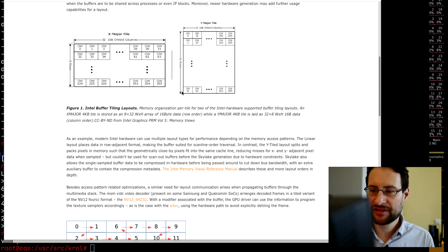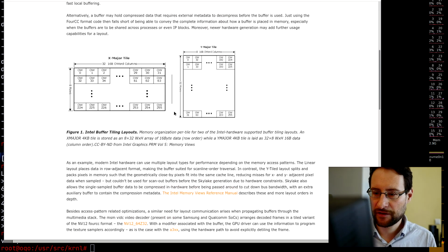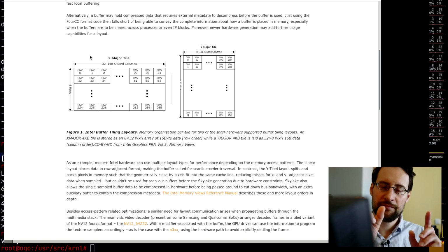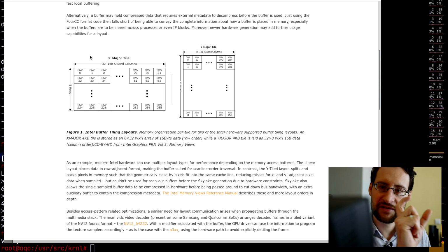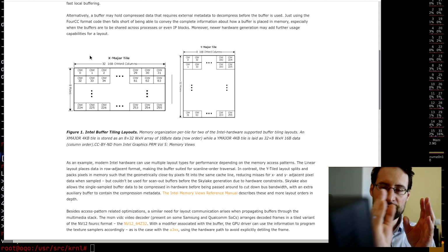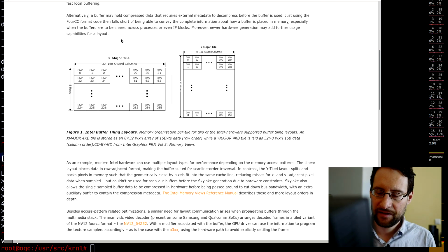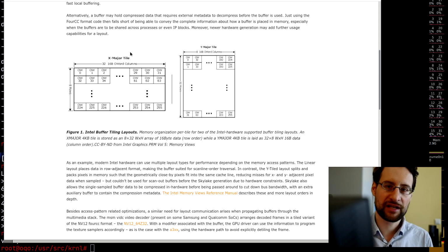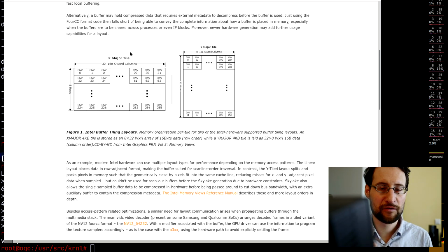But yeah, hope you learned something also, that stuff doesn't need to be stored linear. Stuff can be tiled, swizzled, and why certainly. You see, this is a little bit for the hardware. For the hardware it doesn't matter much, similar to my memory controller video for the SDRAM on the FPGA. Swapping this in hardware is super easy. You just, in Verilog or so, move some bits around, basically XY. You just move the bits in the memory addressing, and it's super easy. It's basically free, not any performance penalty. It's like moving, rearranging some wires for free.